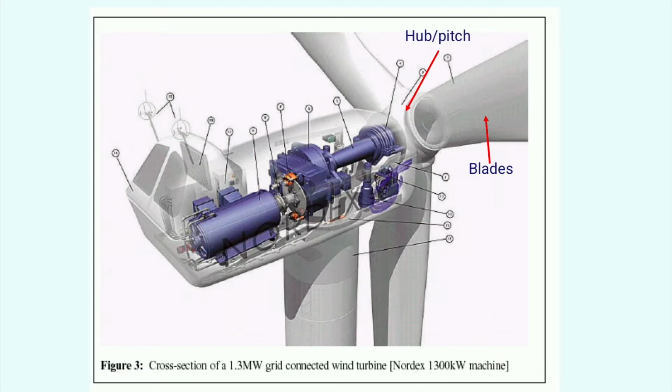The blades are connected to a hub and normally have a pitch mechanism to control the amount of power extracted from the wind. As the wind is ever varying, these actuators see a significant amount of service during the turbine's lifetime. Pitch bearings can get worn, motors can fail, or hydraulic fluid can leak. All of these compromise turbine performance as well as safety and require maintenance.